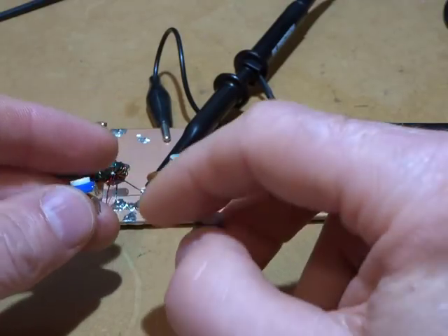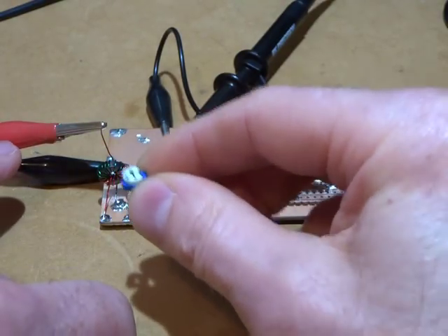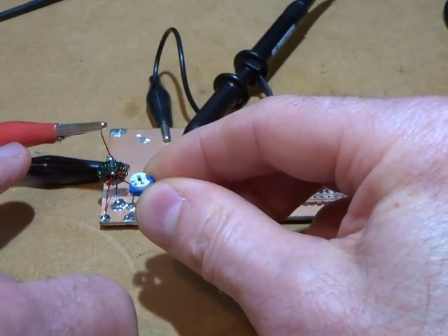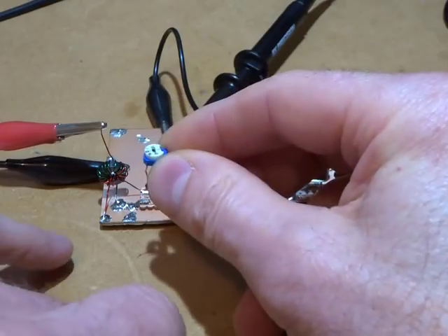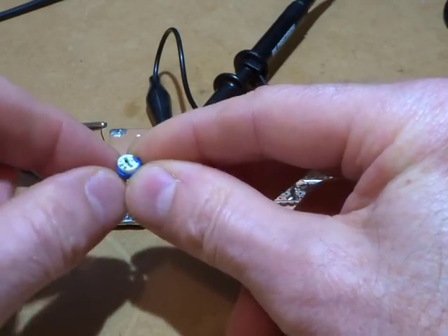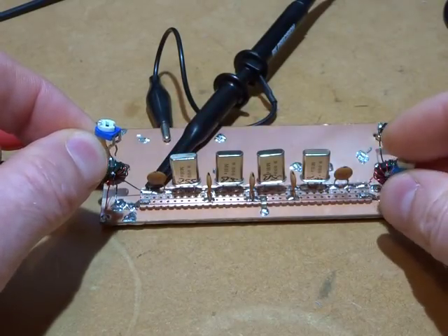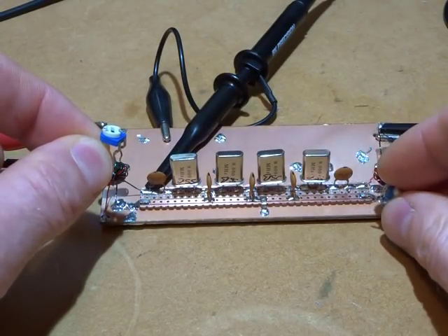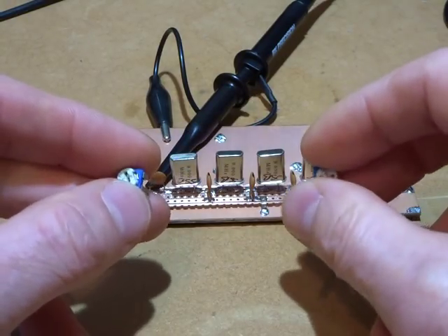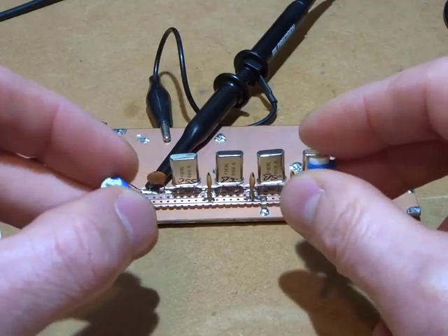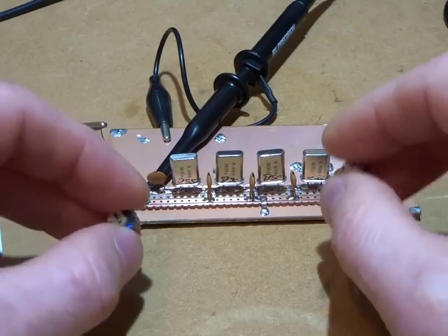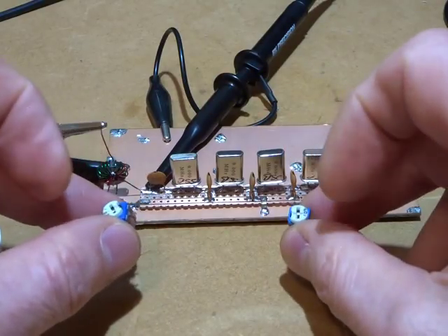The assumption is that the SIG-gen is 50 ohms. So whatever resistance I was using, for example, let's say 100 ohms, then 100 minus the 50 from the SIG-gen would mean 50 here. So this was set to 50, and then the output would have been the full 100 from the output to earth with the scope over top. So that's what I used to very quickly vary the input and the terminating resistor to work out what the passband ripple was going to look like.